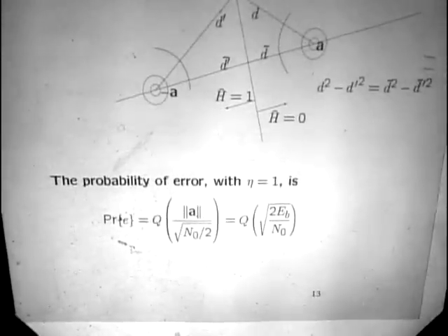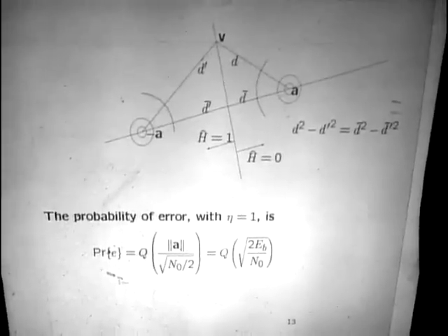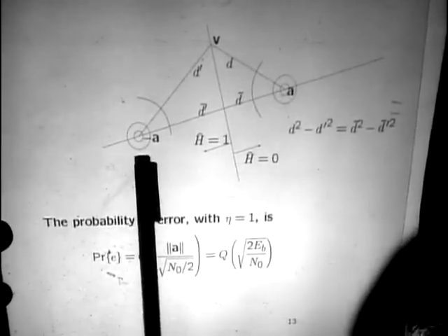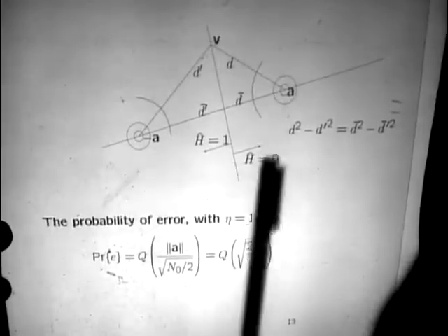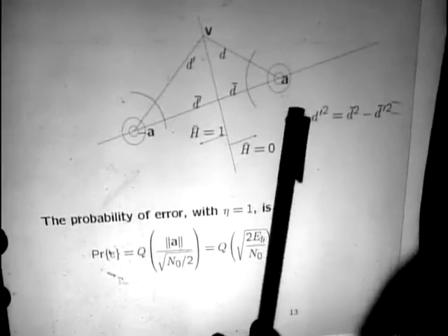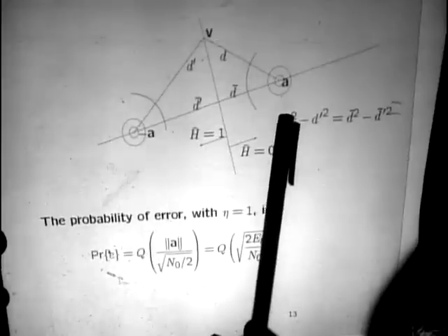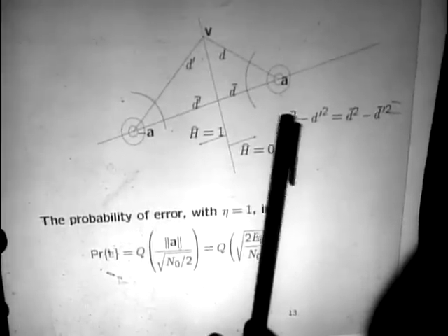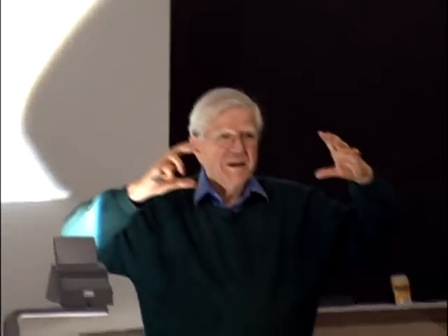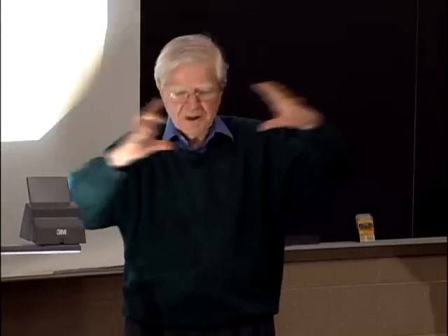Let's look at the picture of this that we get when we just look at the problem when we have two dimensions. So we're either going to transmit a vector A, or we're going to transmit a vector minus A, and think of this in two dimensions. When we transmit the vector A, we have two-dimensional noise. We've already pointed out that two-dimensional Gaussian noise has circular symmetry, spherical symmetry in an arbitrary number of dimensions. So you get these equal probability regions which are spreading out, like when you drop a rock into a pool of water. You see all of these things spreading out in circles.